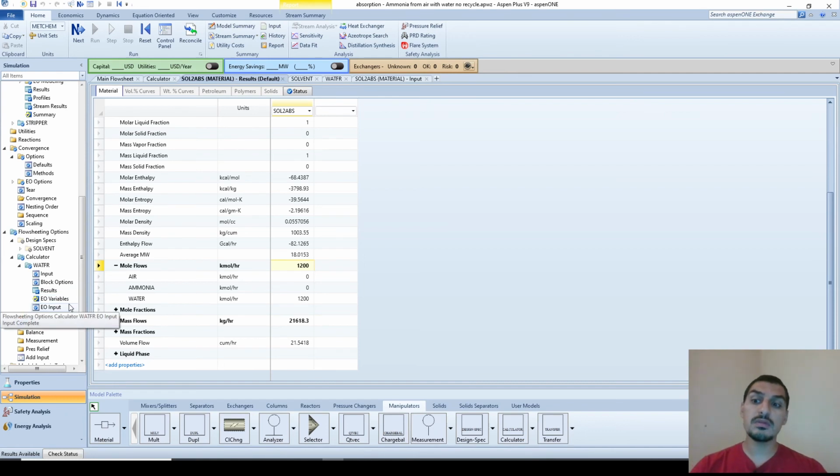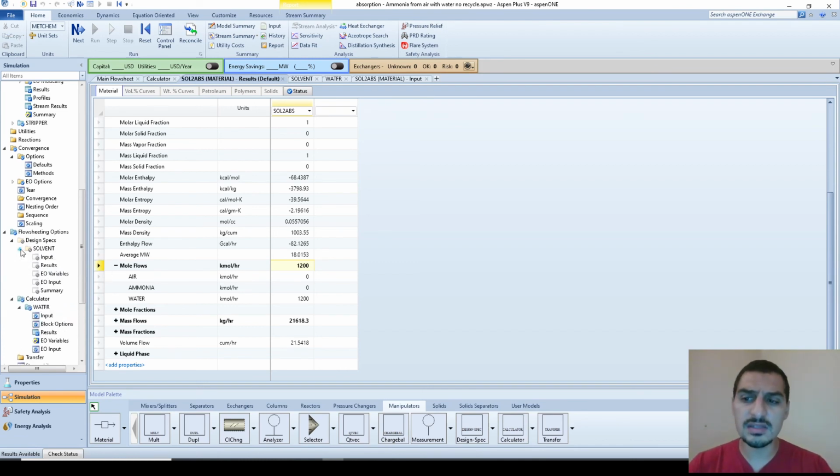There is one thing that you might think of: okay, so I can do this using the design spec. And I have already done this, just for the sake of curiosity to see if it works. To do this, you have to do a tweak so that you can trick the design spec to do a calculation instead of doing the iterative thing to reach a specific goal.